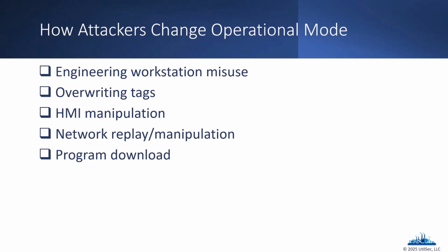And then program download. This is where, again, the OT world is different than the IT world. So when you usually say download, right, a program, it means you're putting it on your laptop. In this case, when we say program download, this means we're putting that firmware or that PLC logic on the controller. That's why I typically try not to say upload or download. I just say we're going to put the logic or that new firmware on that controller.